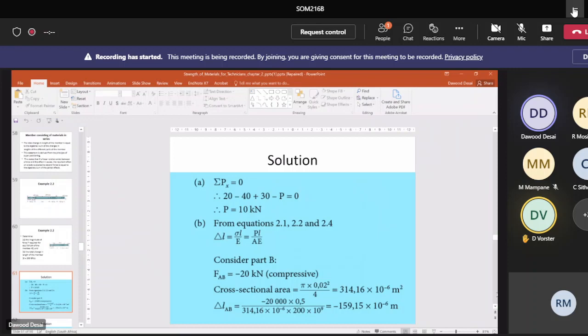Equation 1. What's my second one? Change in length of copper is equal to change in length of steel is equal to total change in length. Equation 2. My work is finished. Now it's mathematics. You can see one way of solving it now.